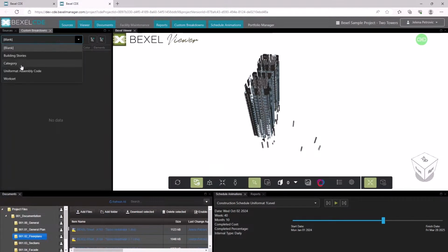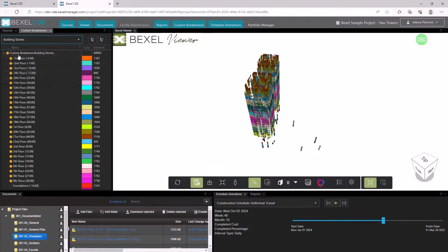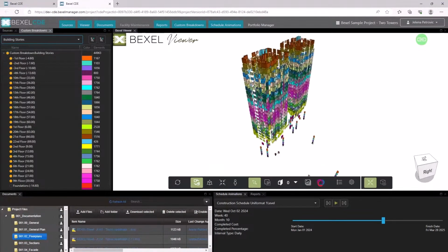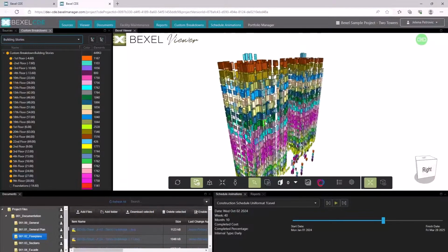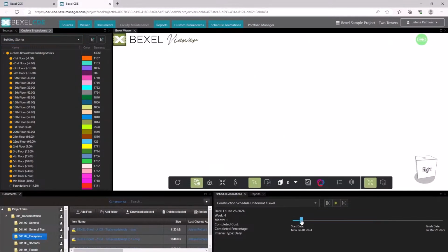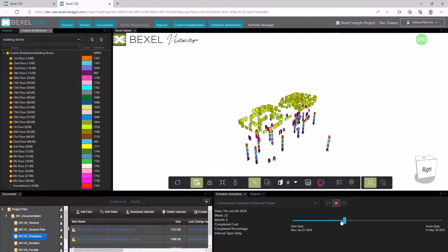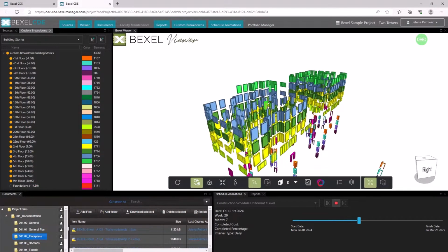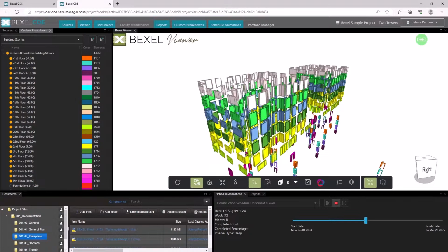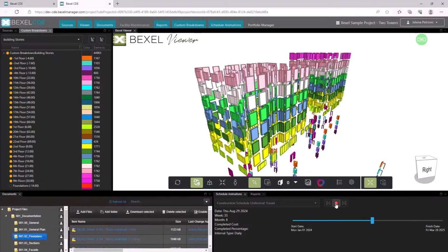Now, when we play animation, it will present only windows and doors, because only these sources are loaded. This is really useful, especially if our model is divided specifically by subcontractor, for example, so we can see animation related to them depending how many sources we have loaded. It can also be divided by stories, so we can see construction simulation only for one story if it is needed.